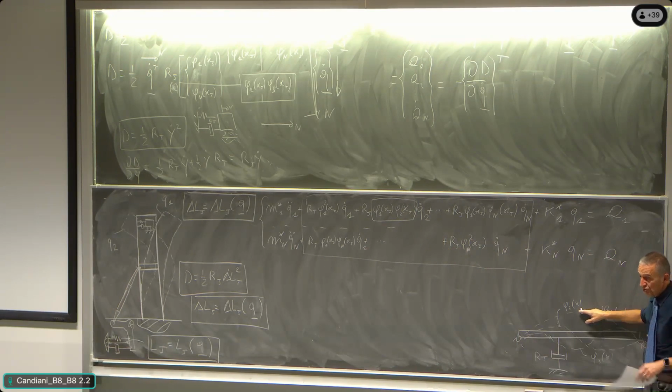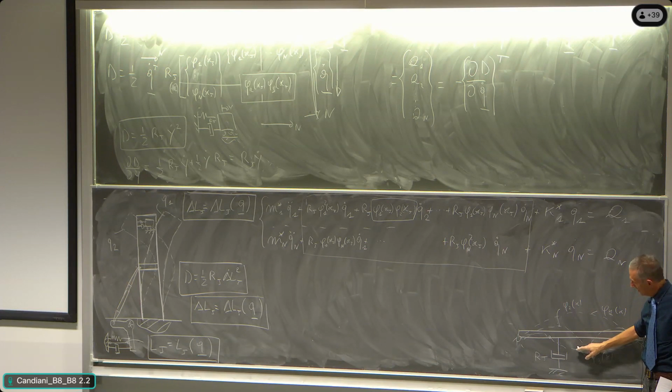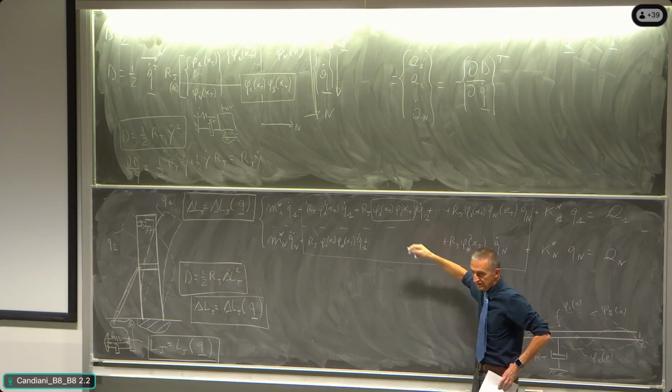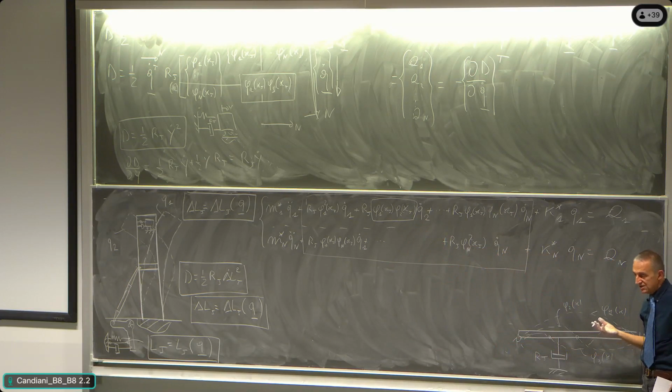So if I want to be very effective with the application of the damper with respect to the first mode, I have to position it in the middle. For the third mode, in the middle. For the second mode, the damper in the middle doesn't do anything. It is hitting the location where phi 2 is equal to 0, all right? But this is very simple, it's obvious, but it is extremely important.